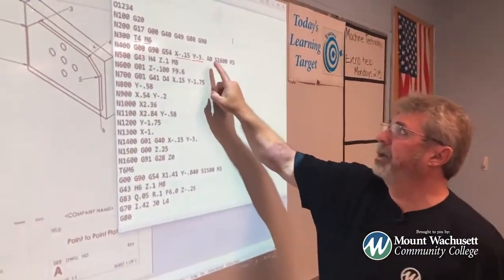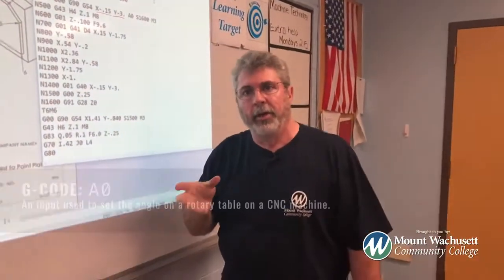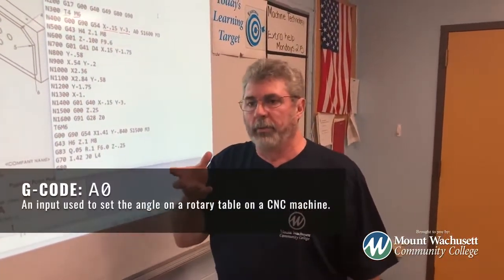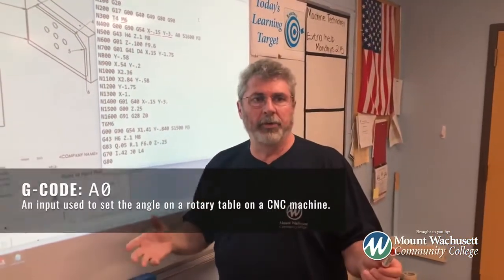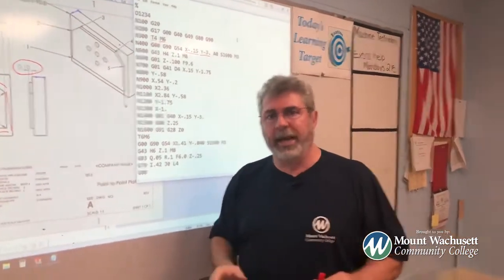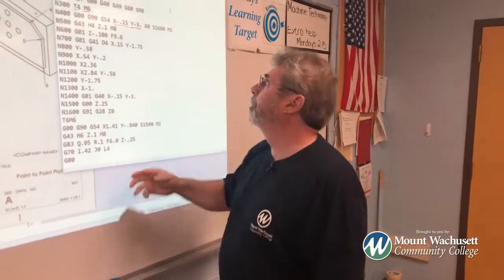Also on this line, A0, which means if I have a rotary table in there, that means move your rotary table to 0 degrees. I'm not running a rotary table right now, but by default or out of habit, I always tell the machine to set the rotary table at 0, just in case your rotary table is off a little bit and you happen to be using it.